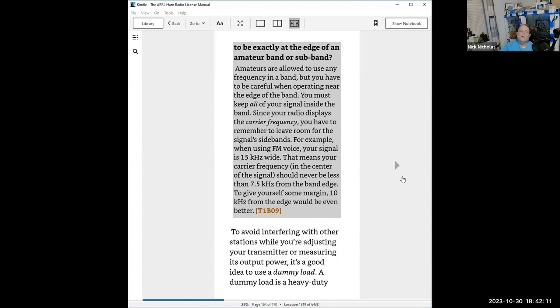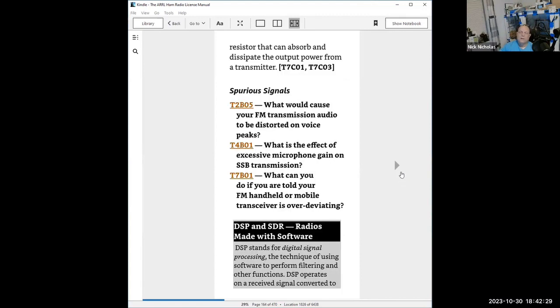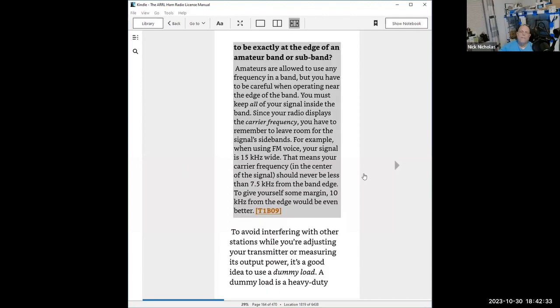Now, I'm going to jump ahead, the book does, so we're going to do it too. I'm going to talk to you about a device called a dummy load. Everyone should buy one. Not right away, but someday in your life, you want to have a dummy load. A dummy load is nothing more than a 50 ohm resistor. And they don't show one. I forgot. I remember now. It's nothing more than a 50 ohm resistor that is a pure resistive resistor.